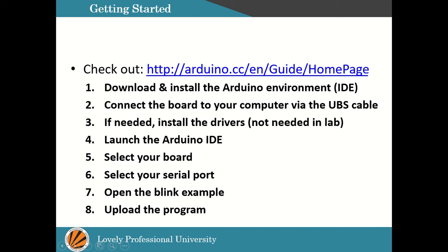Once you have downloaded and installed the Arduino environment on your laptop, the next step is to connect the board to your computer via USB cable. Sometimes the USB cable is detected but the port is not visible once you open your Arduino IDE. What you can do is update your drivers or install the drivers as per the requirement.